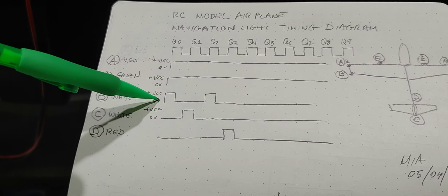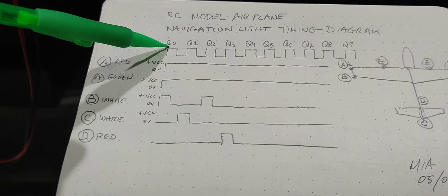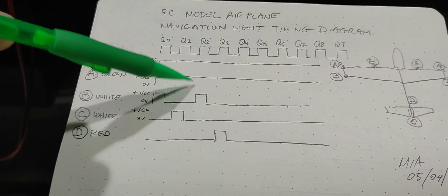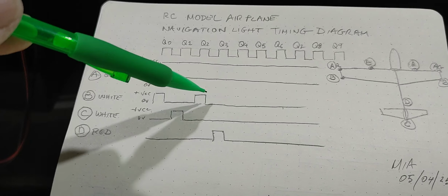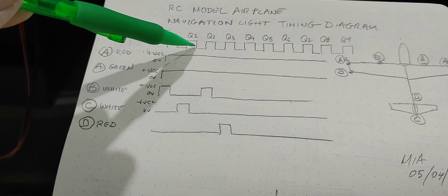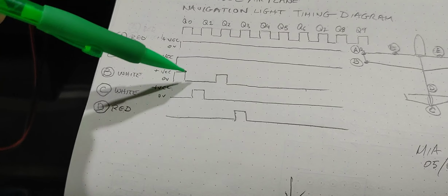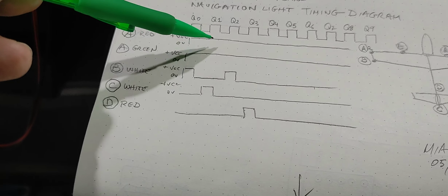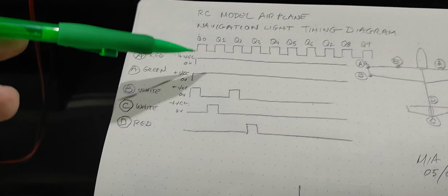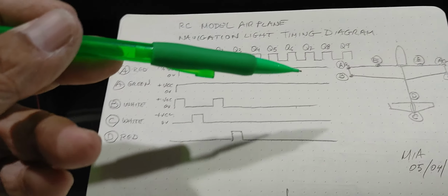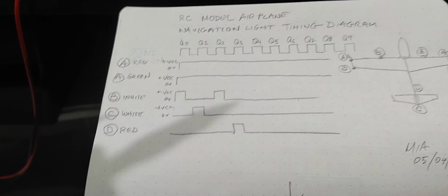So what I'm doing here is I'm strobing at outputs Q0 and Q2. I'm skipping the 1 here because I want that delay. Otherwise, it would just show as the LED full on for these 2 consecutive pulses. So I'm breaking that pulse rate by skipping this trigger from the 4017 output Q1, which would be the second pulse, because this is a decade counter. It's a ripple counter, so it counts 1, 2, 3, 4, 5, 6, 7, 8, 9, 10, 1, 2, 3, 4, 5, 6, 7, 8, 9, 10, so on and so forth.